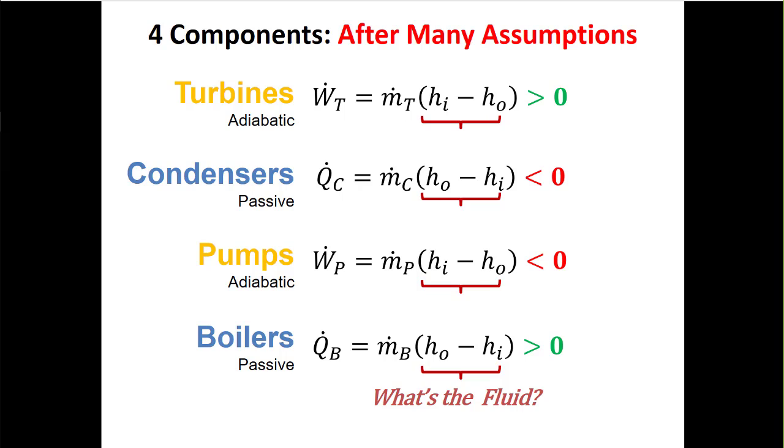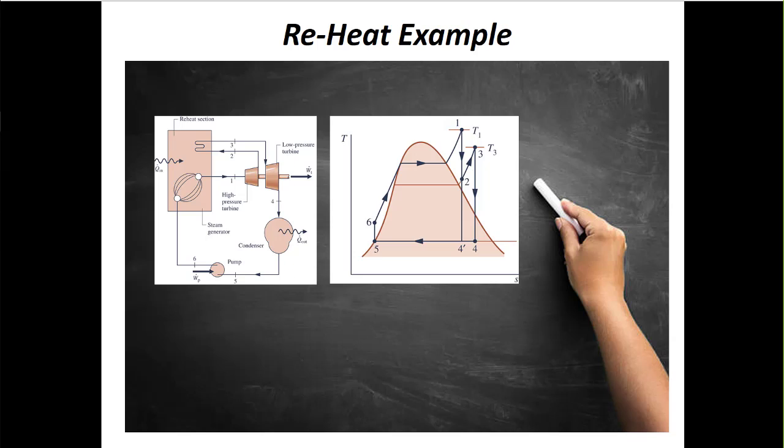Because we're still talking about Rankine cycles, it's some kind of fluid that's going to bounce back and forth across the vapor dome. So that means we're going to ask ourselves not just what's the fluid, the answer is probably water in this case, but then we have to ask, what's the phase? Is it liquid going into a pump or coming out of a pump maybe? Is it a superheated vapor maybe going into a turbine? Or is it a two-phase mixture maybe coming out of a turbine? And when I get that, then there are different strategies for how I go through and fix those states.